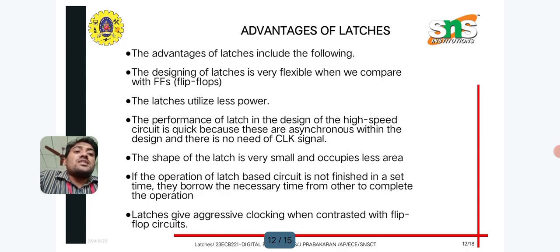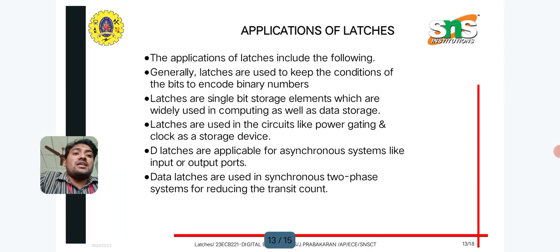The performance of latches in the design of high speed circuits is quick because these are asynchronous in design, and there is no need for a clock signal. The shape of the latch is very small and occupies less area. Latches give aggressive clocking when contrasted with flip-flop circuits. These all are the advantages of latches.